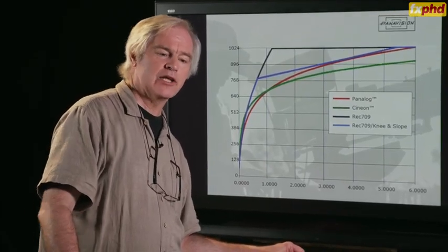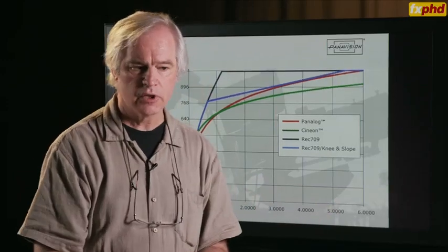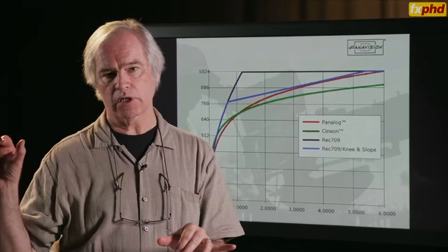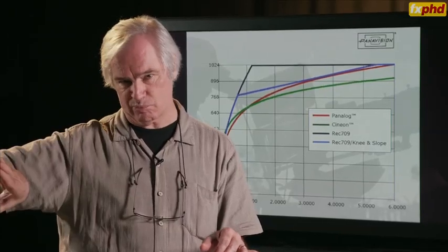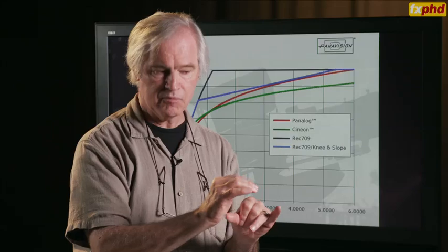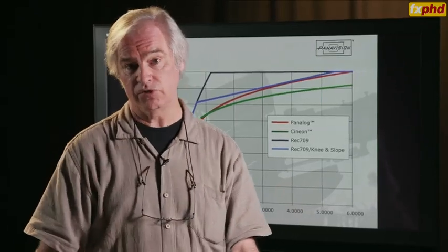For this class, I've been telling you about the overall pipeline from acquisition to display. I've explained a little bit about mappings out to the display and how gamma might have to change depending upon display conditions and viewing conditions. I've explained how the historical 709 standard really just talks about the camera mapping, which is not the important part. Now we've got a really good standard for HD at the back end, BT.1886, that says 2.4 gamma. We've already got a really good mapping at the back end for cinema, standardizing gamma 2.6.